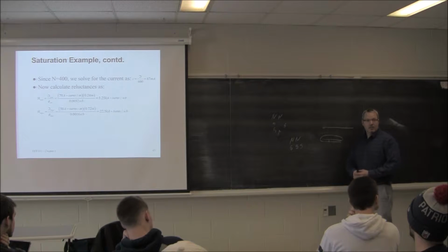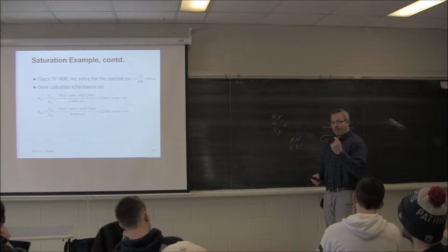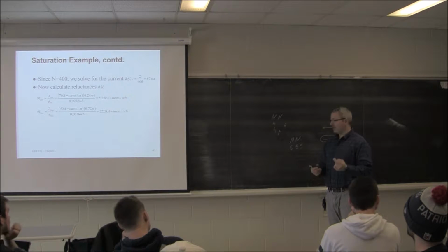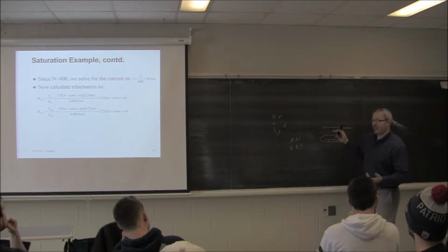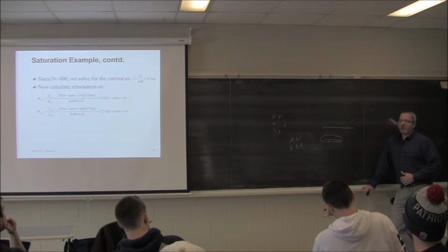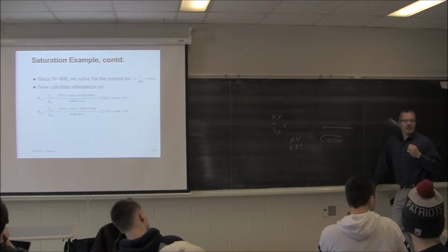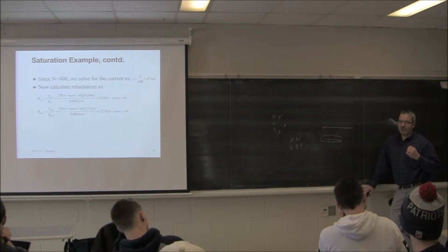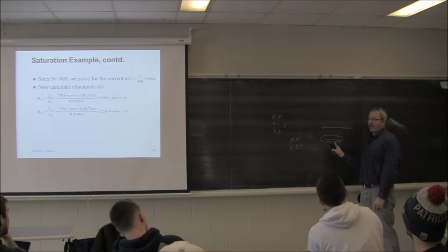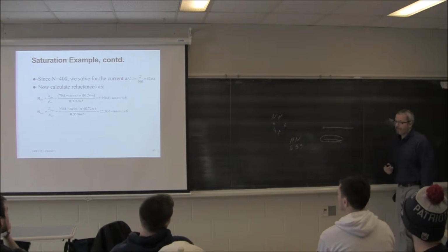Just copper with a lacquer on it. Exactly. It's copper with an insulation. They put a very thin level of insulation, lacquer, if you buy magnet wire, because the voltage difference between turns is a tenth of a volt, or 0.3 volts. It's a very low voltage. So magnet wire is just regular wire with a very thin insulation. That's the only difference. How you get the magnetic field is I run many, many turns through a core, and then I can get lots and lots of magnetic energy. Okay?